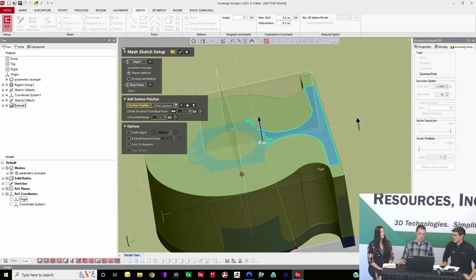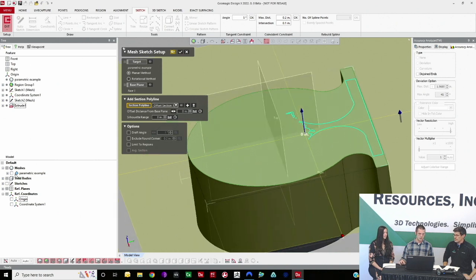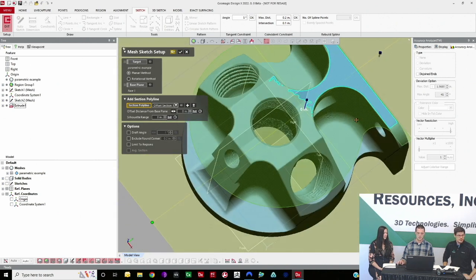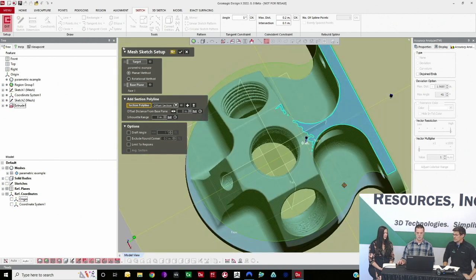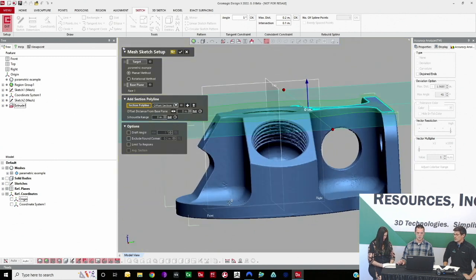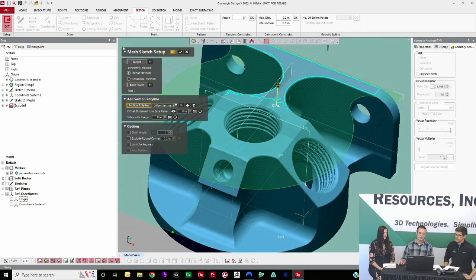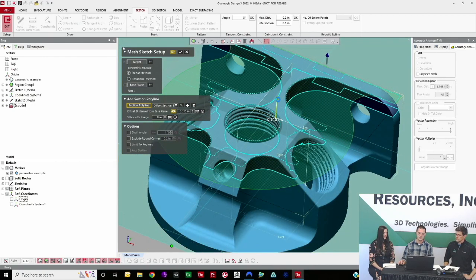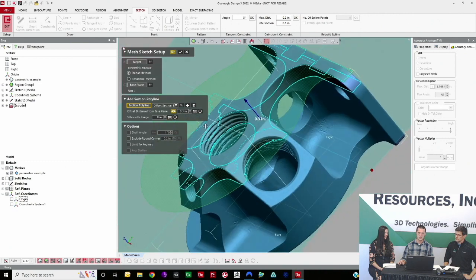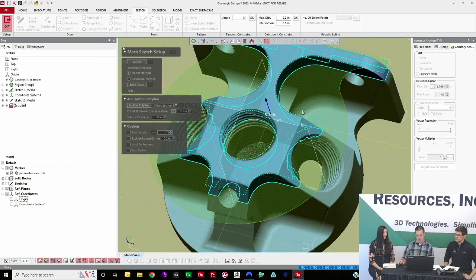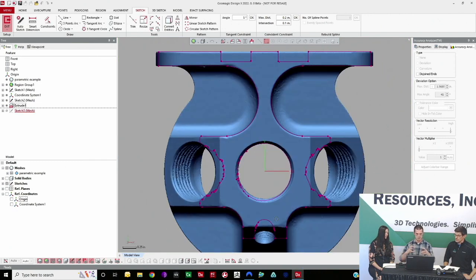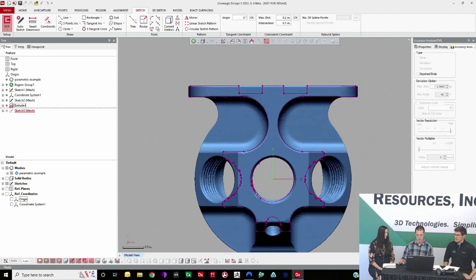All right, so I'll go ahead and perform these two extruded cuts, these 4 windows here. Like I said, I'm assuming these are coplanar. We'll find out here in a second. Once we actually perform the cut, we can adjust accordingly if they're not. But I'm going to go ahead and do another mesh sketch. It's going to be mesh sketches after mesh sketches after mesh sketches, especially with parametric and prismatic parts like this. You're going to be mesh sketching a ton.